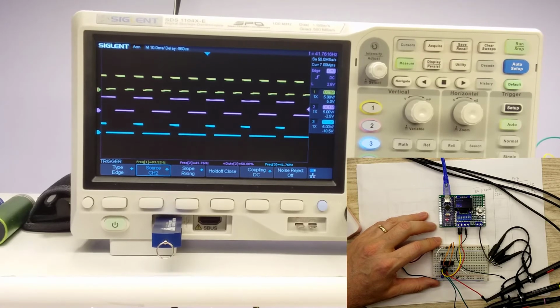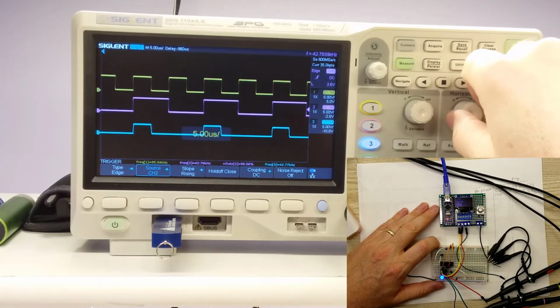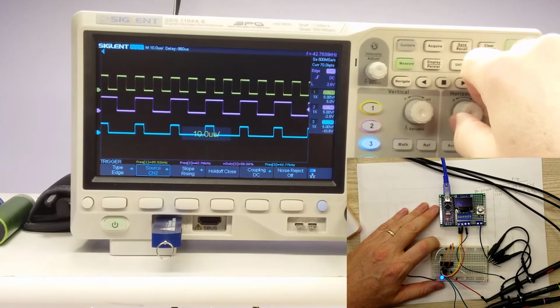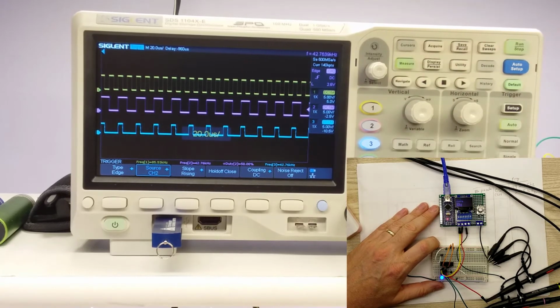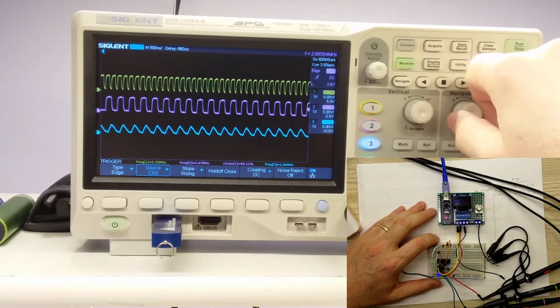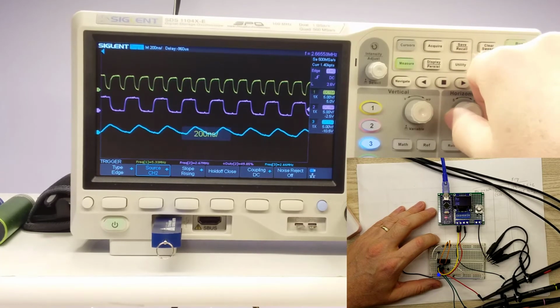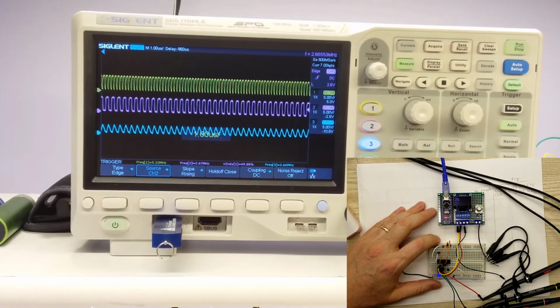And at this low frequency, you can see the LED blinking, and it's keeping up just fine. Now I've got it at about 85 kilohertz, and that is looking really, really good as well. That is a very nice square wave, and I don't see any anomalies on that whatsoever, so it's working really well there. Let's crank that up to 5 megahertz and see what it does. Now I've got that running at about 5.3 megahertz, and kind of like the other ones as well, it looks like it's actually holding up really, really well. It's not really a square wave on the output anymore. It's a little bit more of a triangle wave, but it is definitely keeping up just fine.